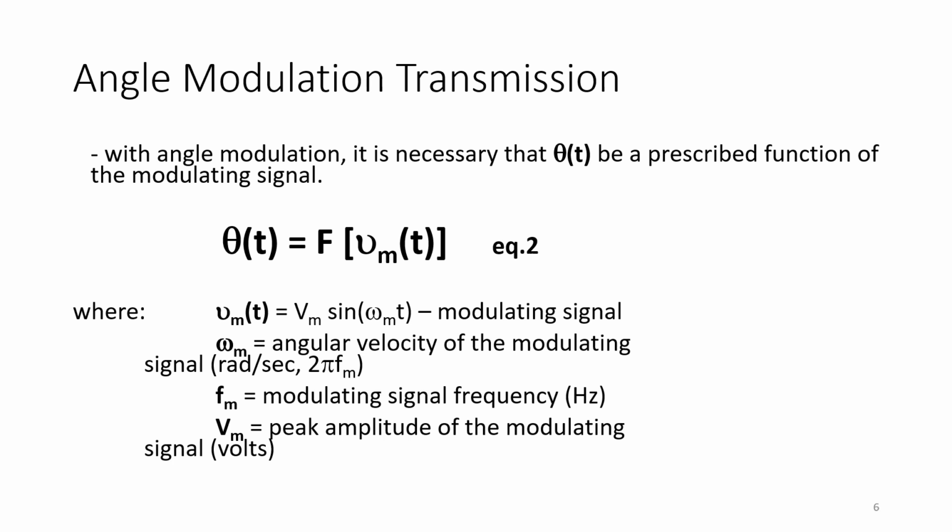So if the frequency of the carrier is varied in accordance with the modulating signal, FM results. When we are directly varying the frequency, FM results. If the phase of the carrier is varied directly in accordance with the modulating signal, PM, or phase modulation, results. Therefore, direct FM is indirect PM, while direct PM is indirect FM. You have to remember that. So this is our second equation.